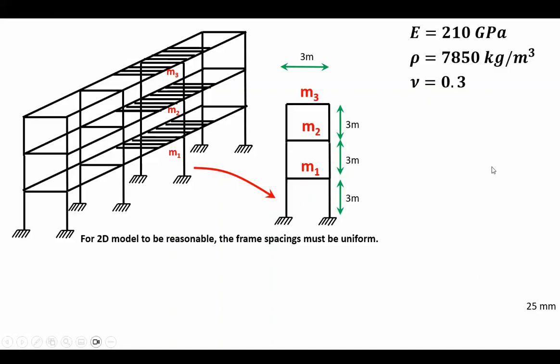Because we're going to use this as a lumped parameter system, we're going to reduce the density of the steel dramatically by a factor of 10,000, and instead use the dimensions and this density to come up with the values M1, M2, and M3.